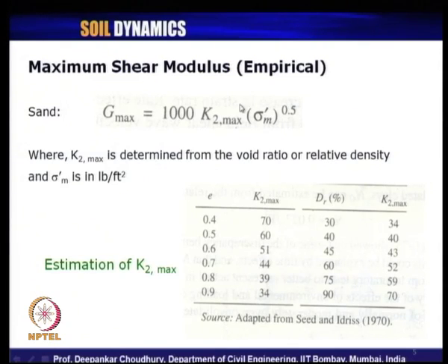Then we have seen several empirical relations to compute the maximum shear modulus, and I have also mentioned cautions in using the empirical relations. First of all, we have to be very careful in which unit they are proposed, because all empirical relations are unit biased.